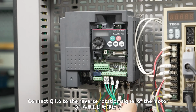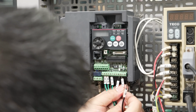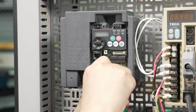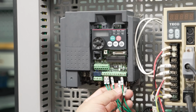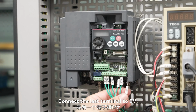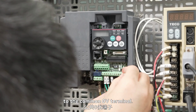Connect Q1.6 to the reverse rotation signal of the motor and use the 10th terminal. Connect the last terminal to 0 volt, and connect all the signals back to the common 0 volt terminal.